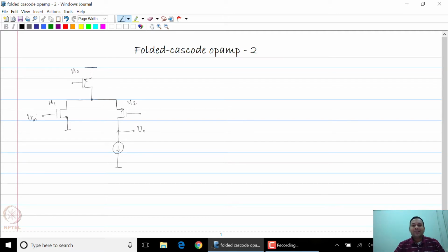Now how do you make a current source? You of course cannot make ideal current sources in practice. So the first thing you try to do is to replace that with a transistor. So please note that the output impedance of this, maybe I'll call that R up, is something we need to write down. Before we move on to replacing the current source, because this is going to become significant in a few minutes, what is the expression for R up?